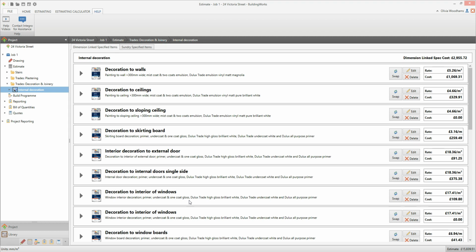Over to you. Draw the existing property, ensuring each element is drawn as an existing, non-estimated element. Navigate your way to the Rooms tab in your drawing. Click the Survey All Rooms button to identify the rooms in your design. Then click on each room and select a name from the Name drop-down box. Once your rooms have been named, click on a room to select it, then click the Wall and Ceiling Renovation button to begin estimating some renovation tasks for that room. Give it a go.